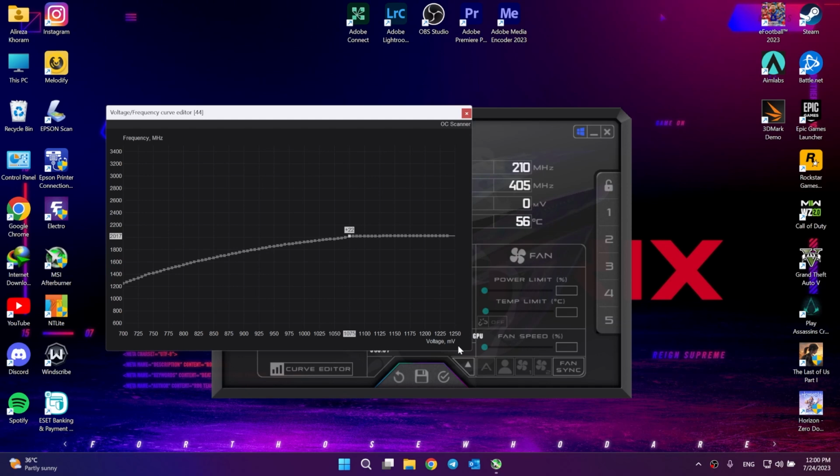Tuning this might take a lot of your time, but trust me, if you do, you will love it. I have reached a spot with one of my configs where it's maintaining almost the same performance while lowering my temperatures in games for like 10 degrees, which is insane. Of course, the benefits might differ from a hardware to another, but who doesn't like lower temperatures? And just as overclocking, undervolting is 100% safe.